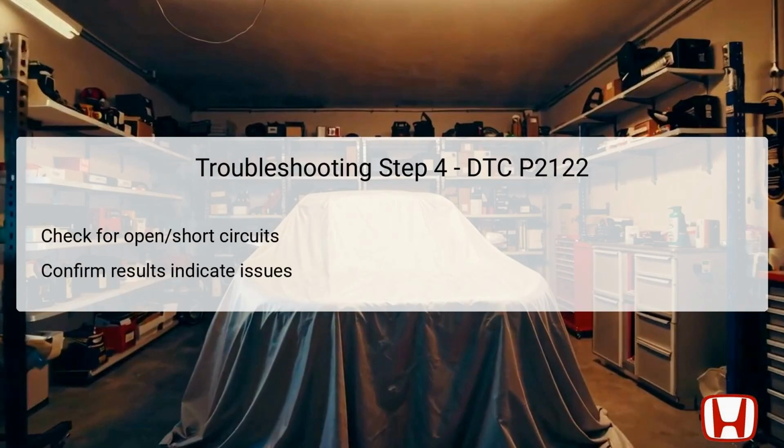In this step, conduct a detailed examination for any open or short circuits within both the APS1 and VCC1 wiring. Utilize an appropriate multimeter to measure resistance, ensuring that the APS1 open wire inspection indicates less than 1 ohm, while the VCC1 check should yield the same result. Any resistance readings above this threshold would suggest a problem within the associated wiring.